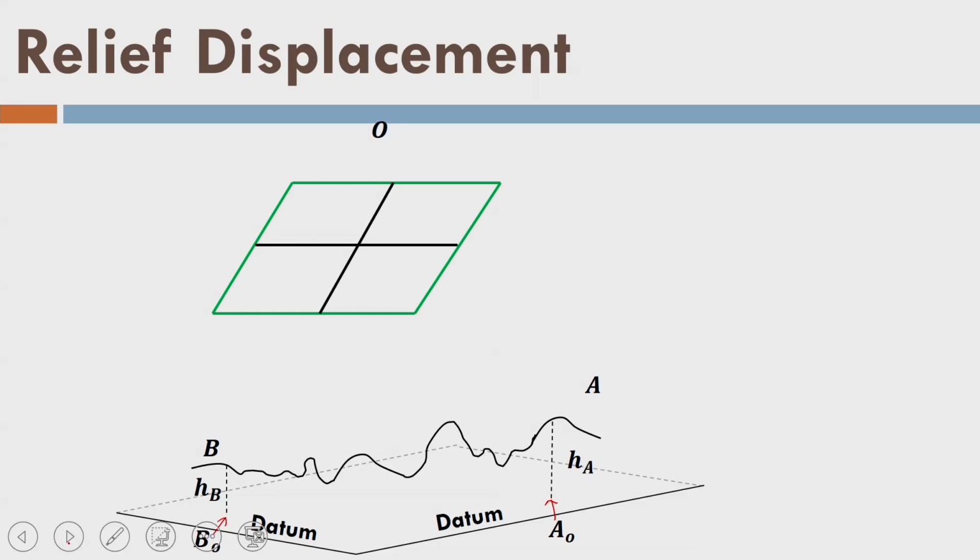There is an image and there is an exposure station, and this is the optical axis, which pierces the datum at K0, with principal point K here. If I extend the optical axis in the gravity direction, it reaches this point here. The height of the point K with respect to the datum is HK.